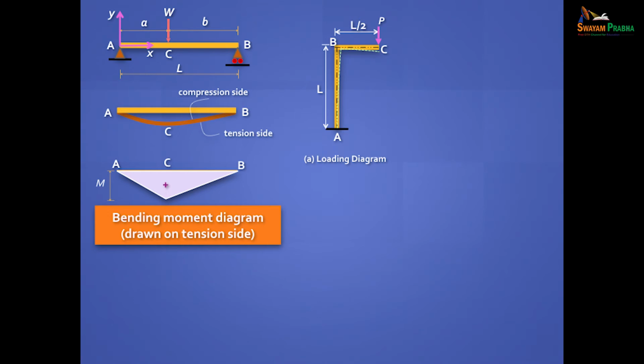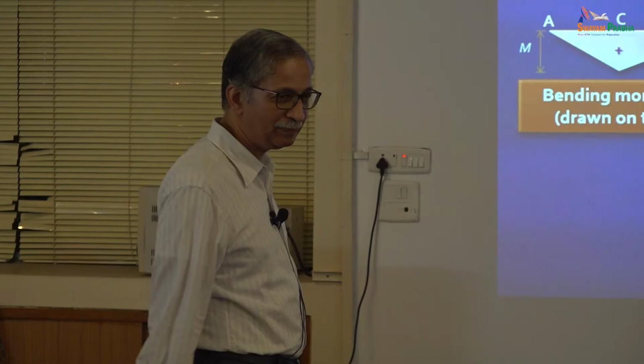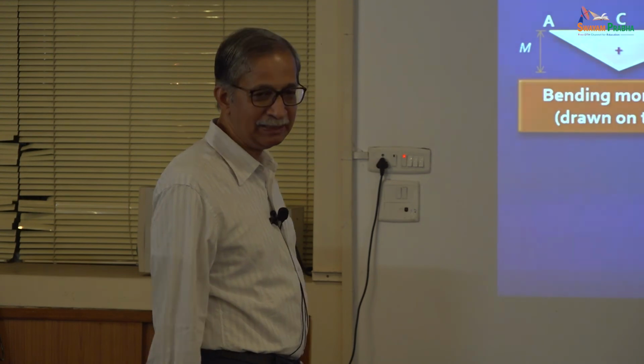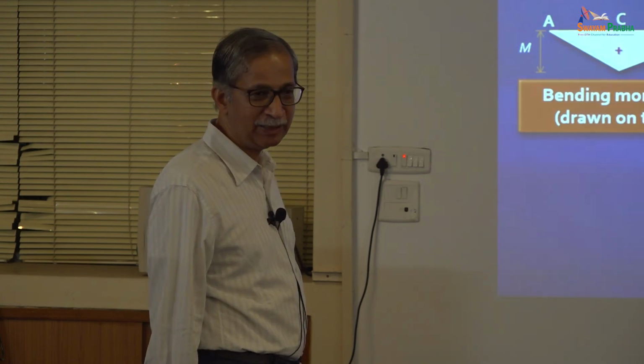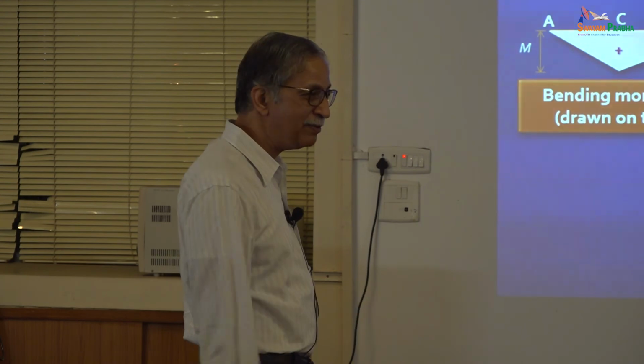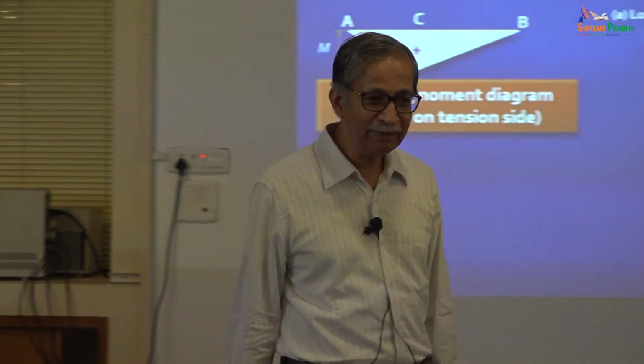Got it? Now instinctively you feel it's going to bend like this, right? Now there is going to be bending moment in AB and BC. So we are moving a little ahead beyond beams into frames. Now, where do you have only bending moment and shear force? In AB or in BC? In BC. You have only bending moment and shear force. In AB, you have something extra. What is that extra thing you have? Axial force, which is compressive. That's the only thing that makes it a frame element.